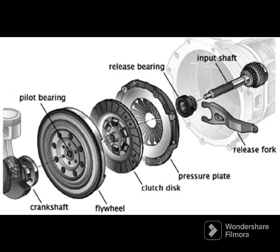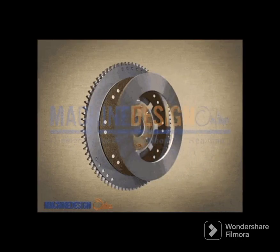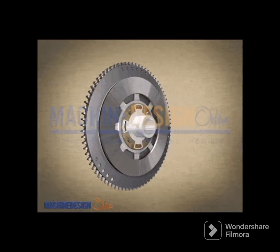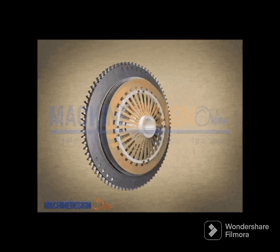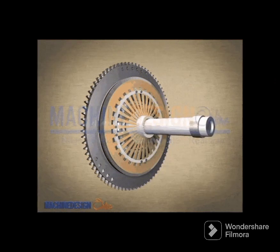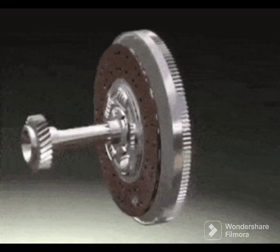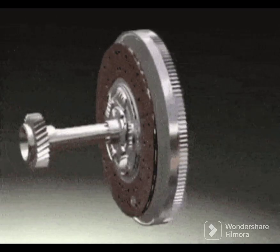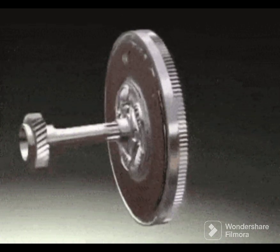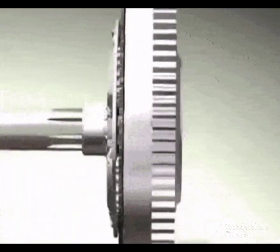The friction clutch consists of two main parts: the clutch plate, also known as the friction disc, and the pressure plate. The clutch plate is located between the engine's flywheel and the transmission's input shaft. The pressure plate is bolted to the flywheel and exerts pressure on the clutch plate through a series of springs or a diaphragm spring. When the clutch pedal is not pressed, the pressure plate applies pressure on the clutch plate, causing it to be pressed against the flywheel.